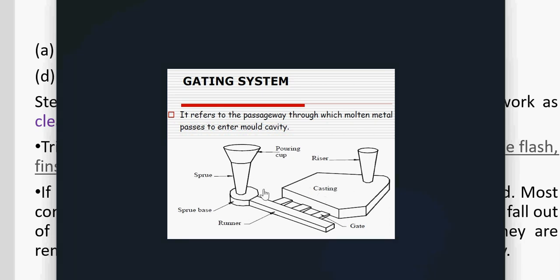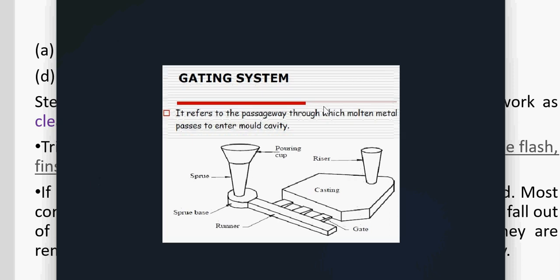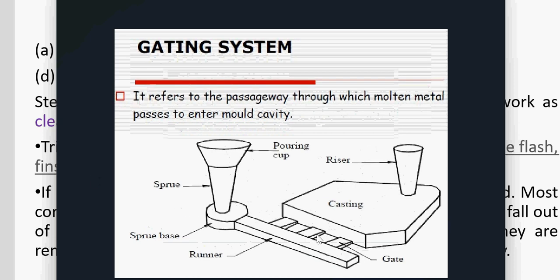Right? That looks so, but this cast is not just like this. You need a mold whereby you pour it through this pouring cup. It will go through this gating system, and there are also risers. All this is to ensure that there is no inclusion of unwanted oxides. After the solidification, all this gating system will be removed. When they are removed, they will leave some kind of rough surfaces, right? In this case, you will have to what? Trim them.